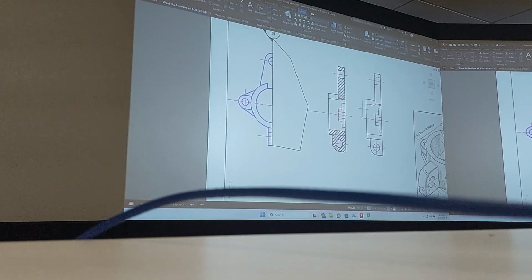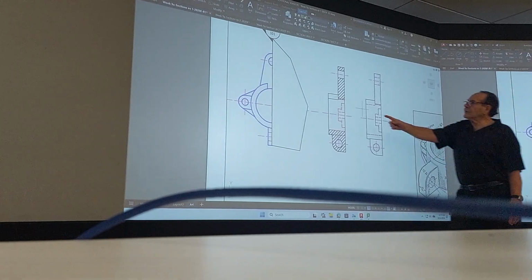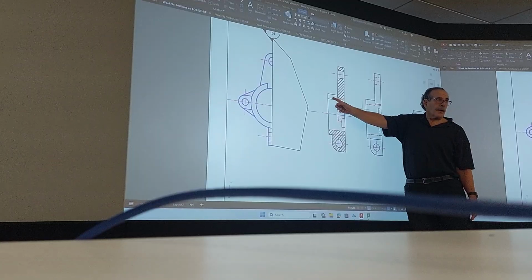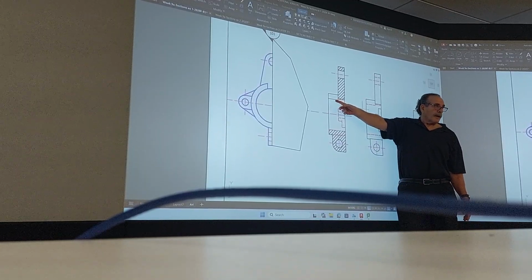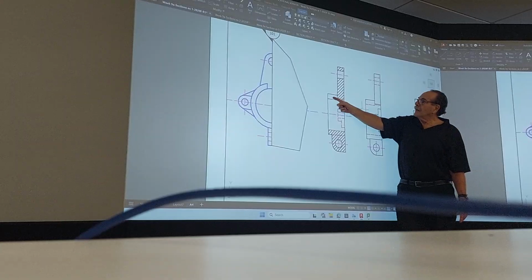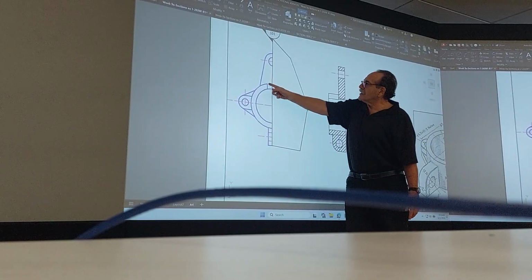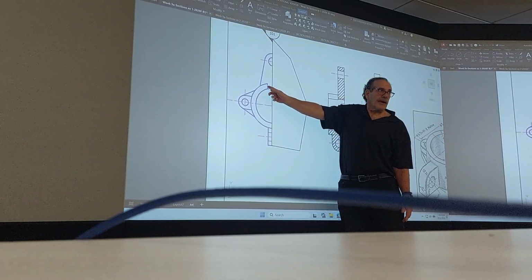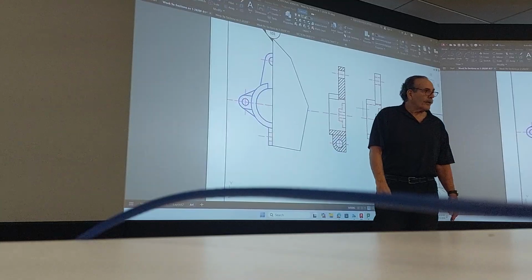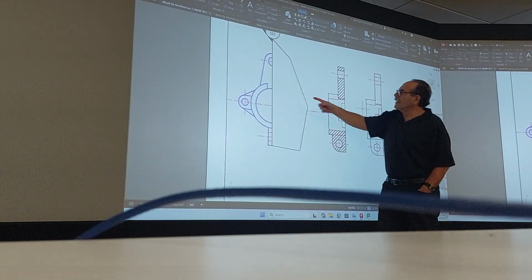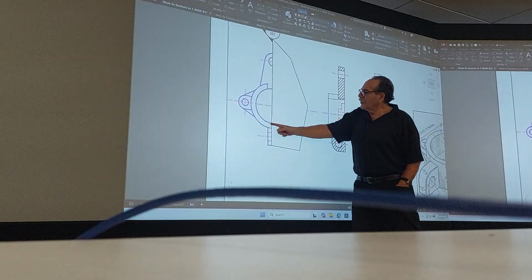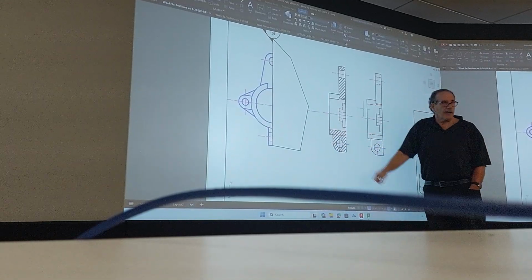Okay, so should this part be hatched? Is it on what you cut through? Yeah, this part is this face here, so we actually see the face. Yeah, only where we cut through, so the hatching is indicating where you cut through. So this part here I leave clear because I'm looking at it, but over here I'm cutting right through it.